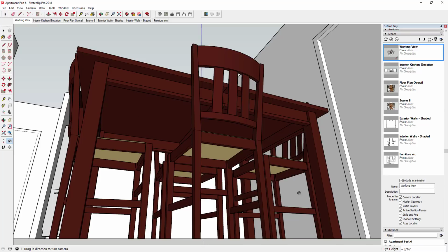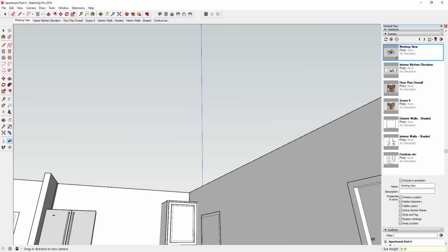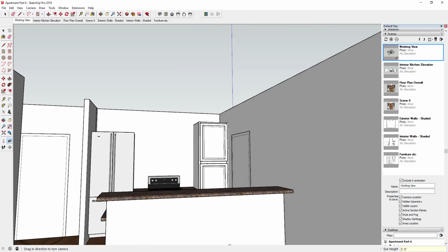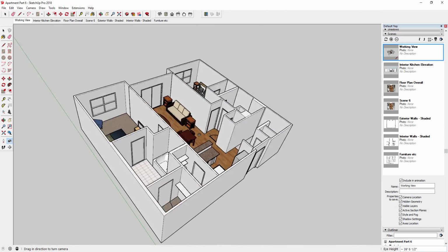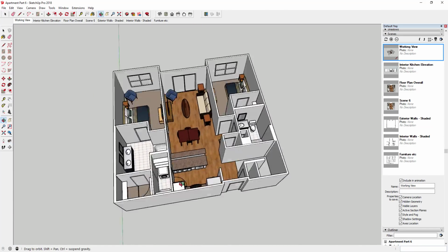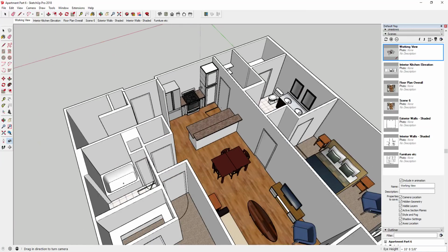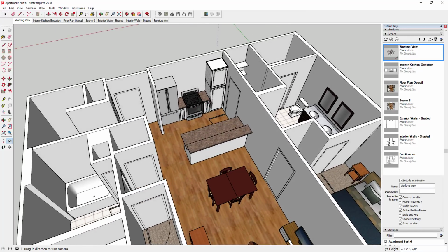Then, down in the lower right hand corner, it lets you set your eye height. So I would set my eye height to like 5'6" or whatever. And then you could click and look around, but you can use that to set your camera. The other thing you can do with that is click and drag and create cut through views without actually doing a section plane in your model.